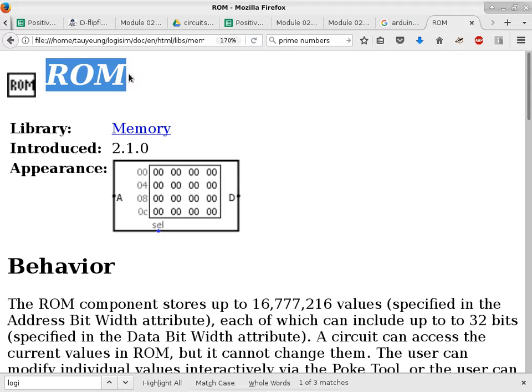P stands for programmable. So programmable read-only memory are chips that are blank to begin with. So they ship it to you blank with no content in it. And then you buy a special device to program it. But it is one-time programmable. So that's why a lot of times, these days, back in those days, they don't use this term, but you can kind of imagine there's an OT in front of the P, which stands for one-time programmable read-only memory.